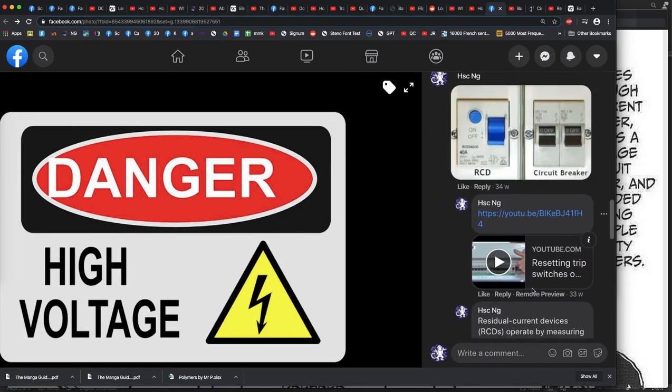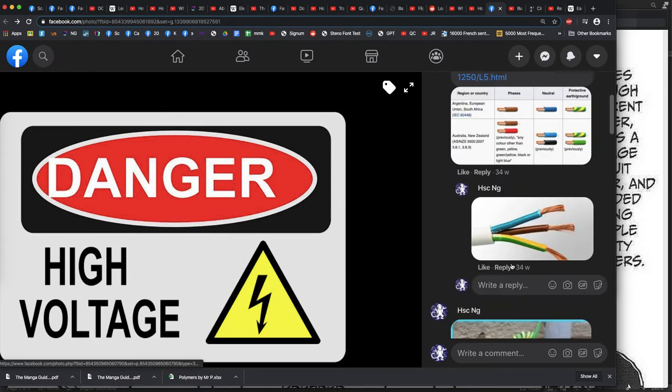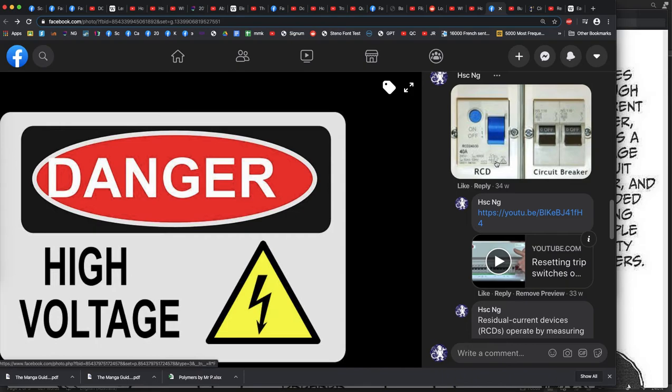Okay, so what are we looking at? Well, we've now seen that fuses have been replaced with circuit breakers. I had this in a question for my preliminary students last year, and they were upset about this. They said, don't houses use fuses? And I said, not modern houses. I'd specified in the question that a new home construction will be protected by earthing, by a circuit breaker, and by an RCD, or residual current device.